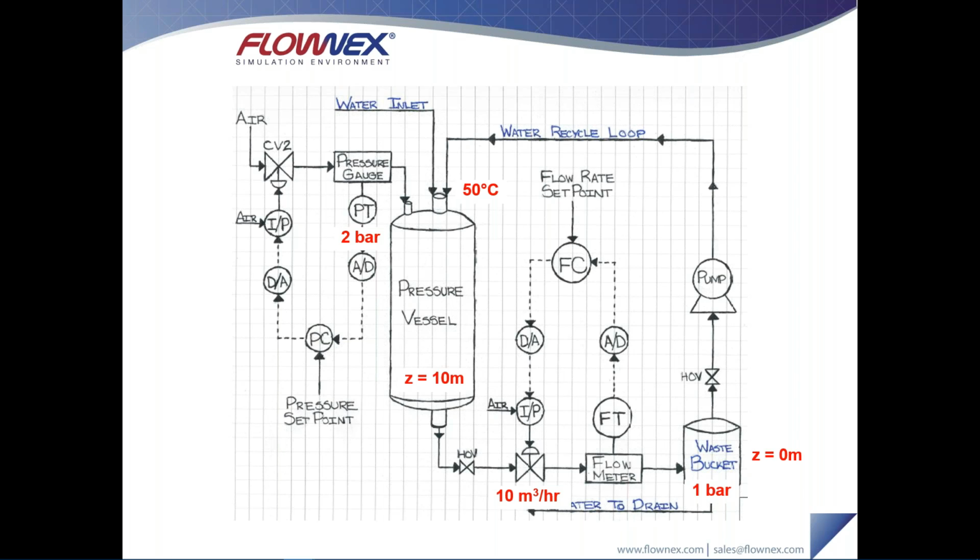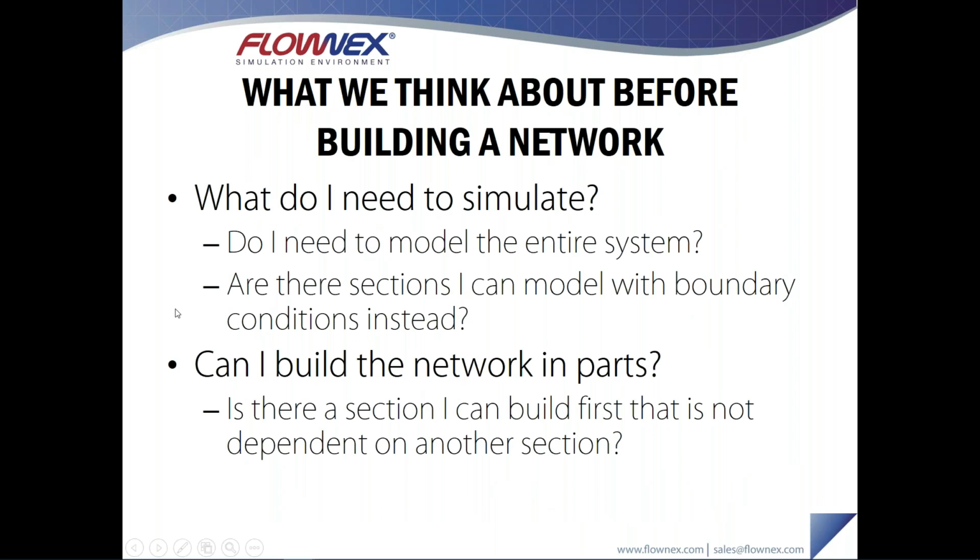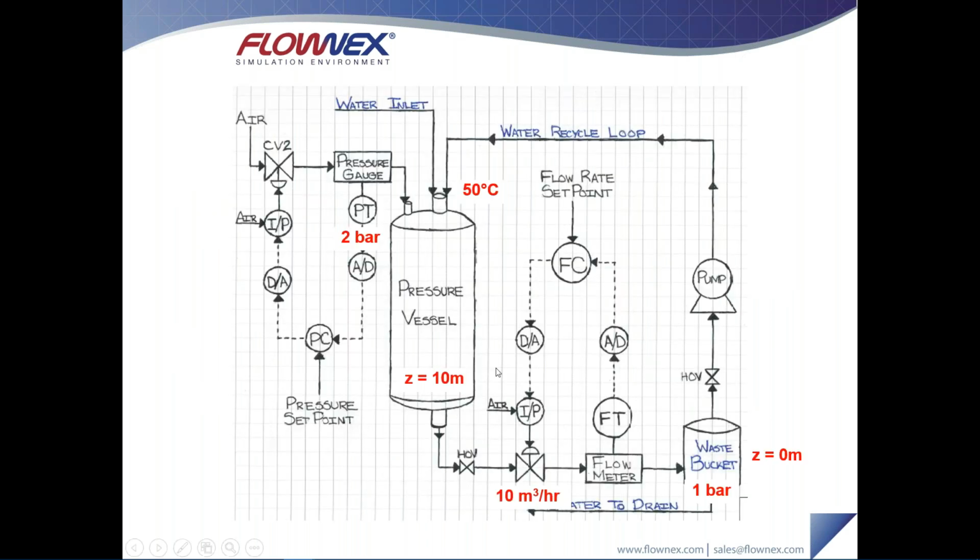We need to first analyze our drawing and start figuring out if everything that we've drawn in our system is strictly necessary to answer the questions that we have. So the next line of thought that I'd like to propose is, what do we really need to simulate? Do we really need to model the entire system? Is it really necessary to model the air system on the left-hand side, this pressure regulation system? Is that going to have an effect on the size of the valve we choose or the size of the pump we choose?